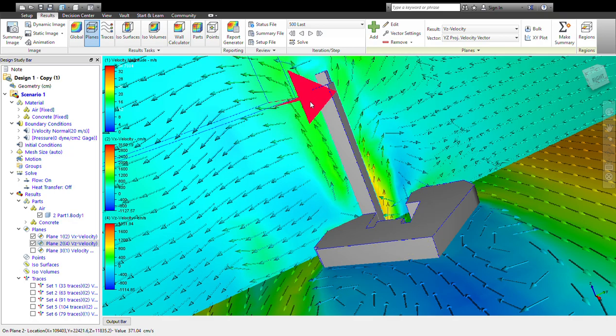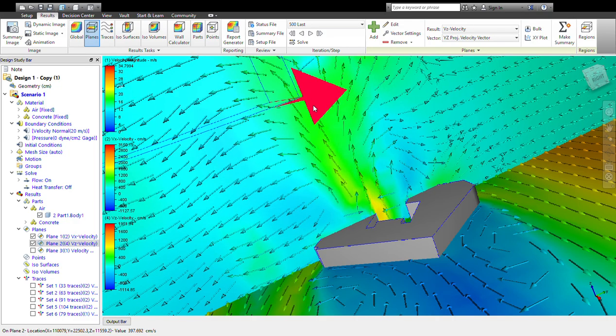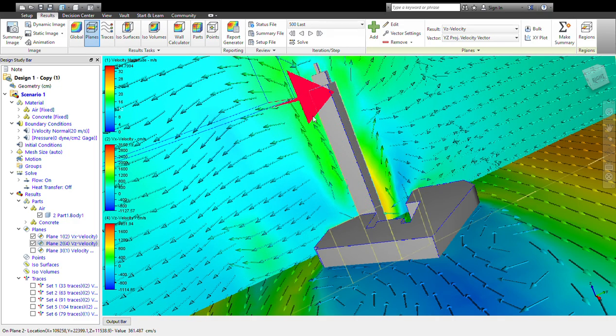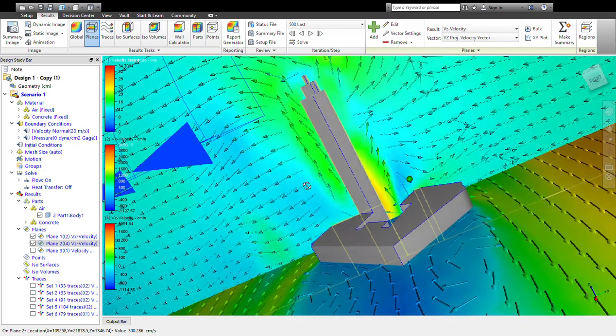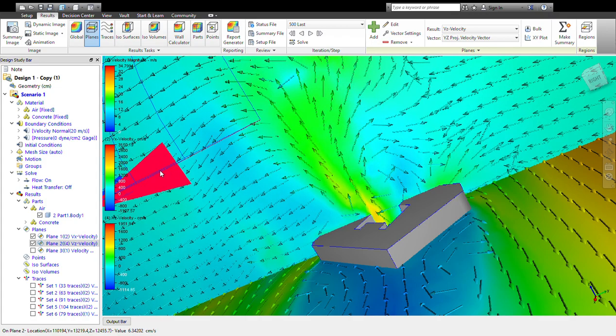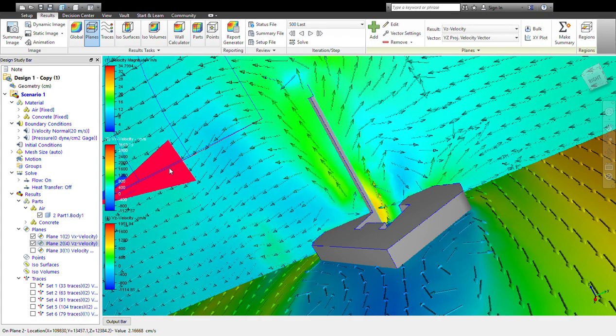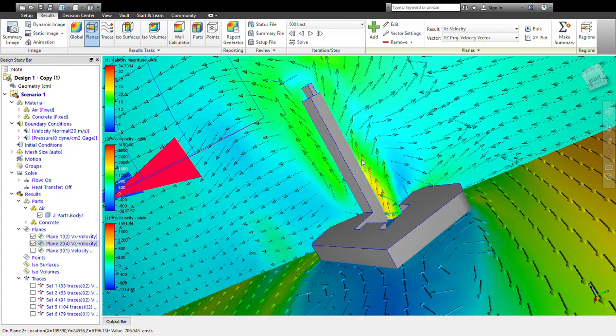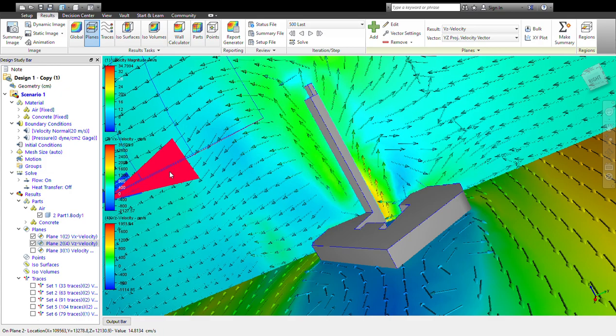Okay, so now we can actually move and analyze the wind, what's happening exactly in this building. Due to the shape of it, you can easily see that the wind is created in the upward direction. So this specific elevation for the facade consultant has to be looked at carefully, and then we understand that there is an uplift wind in this area. This might create some problems if we have vents in this location. Has to be carefully studied, and this additional load has to be analyzed.